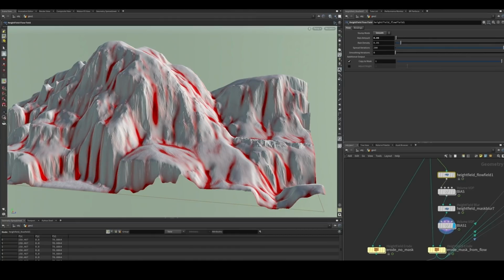A lot of times artists will want to hand paint stuff in or procedurally generate it. Depending on how you set up your HDA in your pipeline, for this we're using it all as an enclosed HDA, so it's almost all procedurally done. But at any point in this process, you can break your HDA up into unique chunks and say, up to here is going to be an HDA. Then an artist will touch it by hand, and then we'll feed the rest back into a separate HDA to continue automating the rest of the pipe.